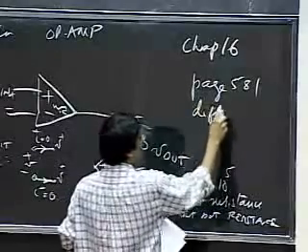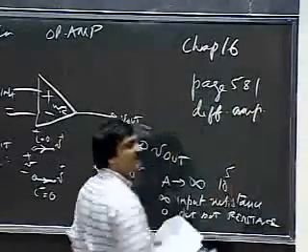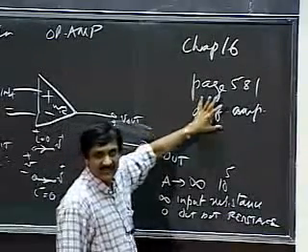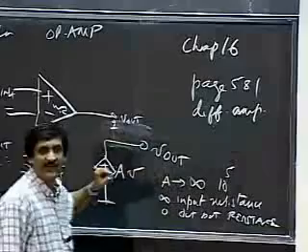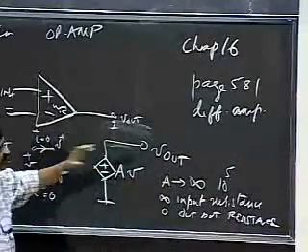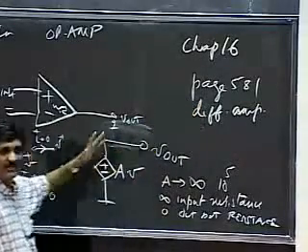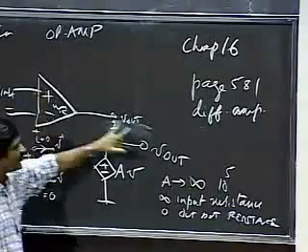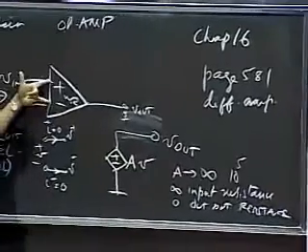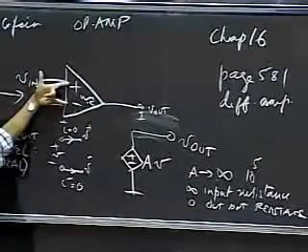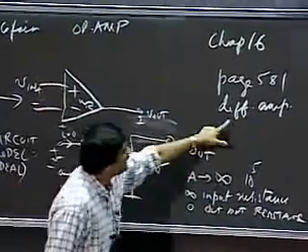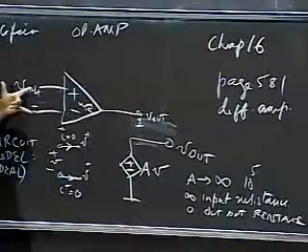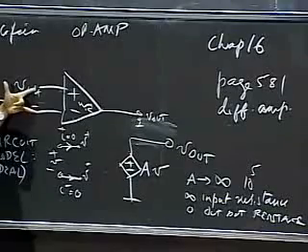for a differential amplifier. This is the small signal analysis chapter. That differential amplifier that's solved in that example is usually the first stage in an operational amplifier circuit, at the input. And that differential amplifier, as the name implies, amplifies not a single voltage, but a differential voltage.